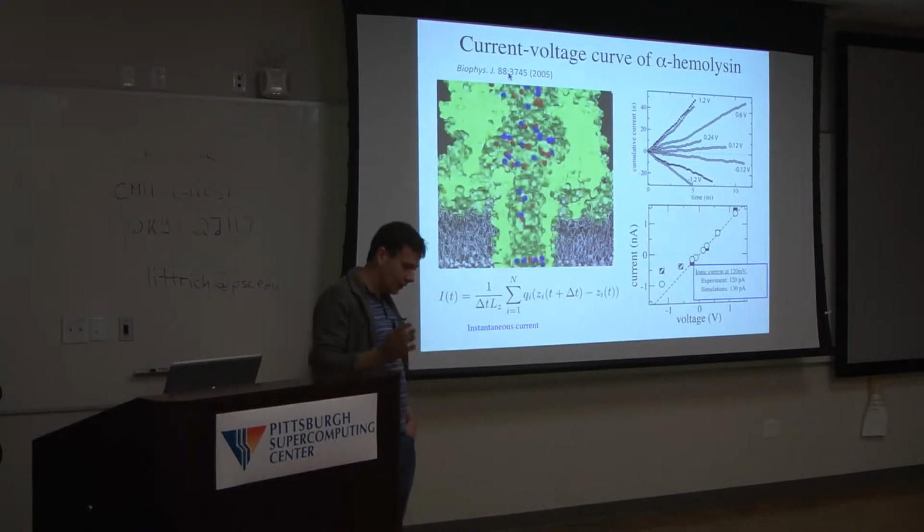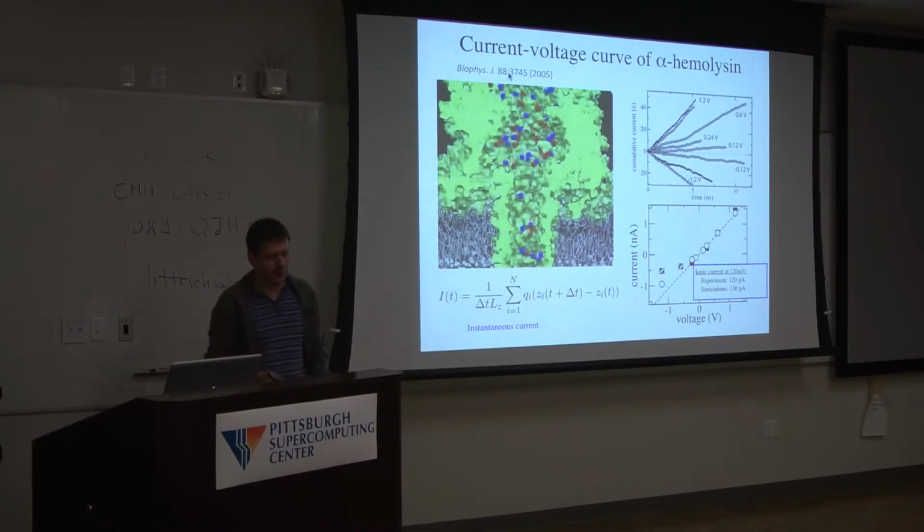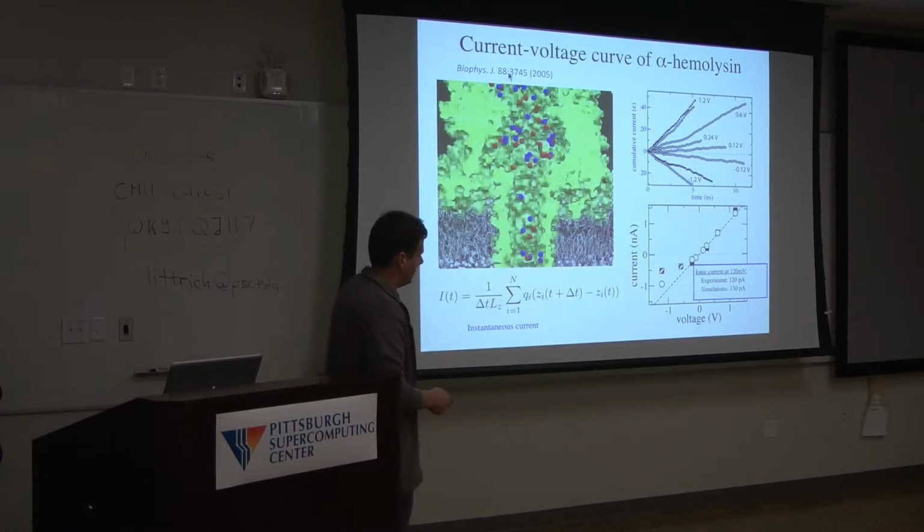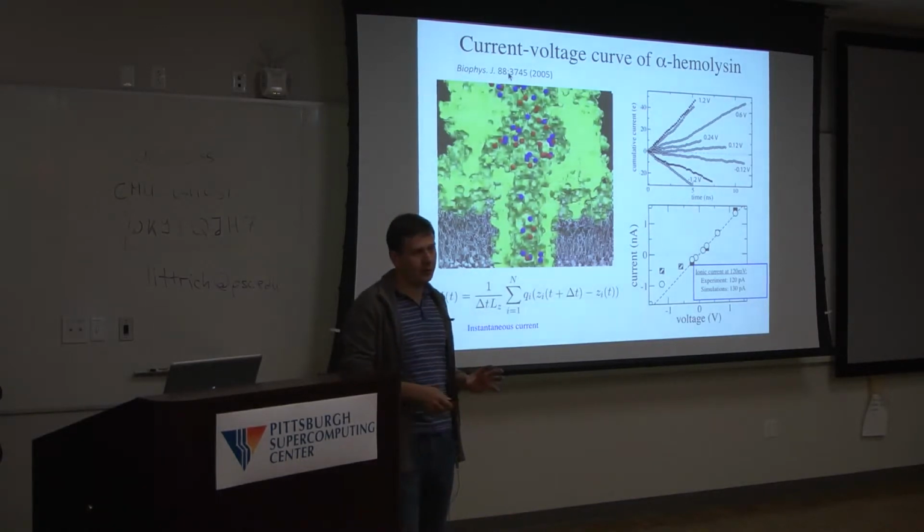So it is a very straightforward simulation, and it is described in the tutorial. It works very well, surprisingly. For example, in this case, experimentally, we should get 150 picoamps, and we got 130 picoamps from our simulation just like that without doing anything. If we change the polarity of the bias, we'll see some slight rectification of the current, just like in an experiment.